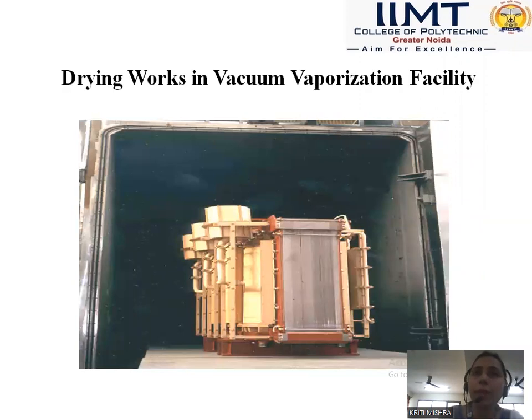This is the VPD, generally drying works in a vacuum vaporization facility. This will remove the vapors from all the transformers, windings, insulations, oils, everything which we have made. If there is a little bit of moisture there, it will be removed through this vacuum vaporization facility.